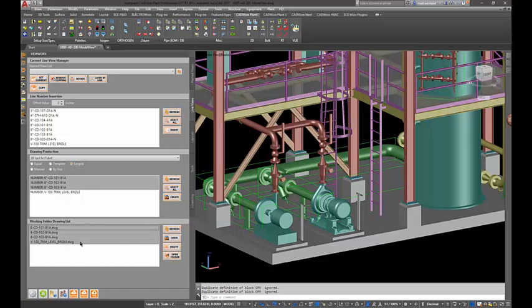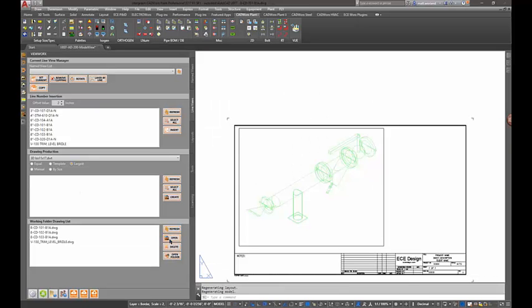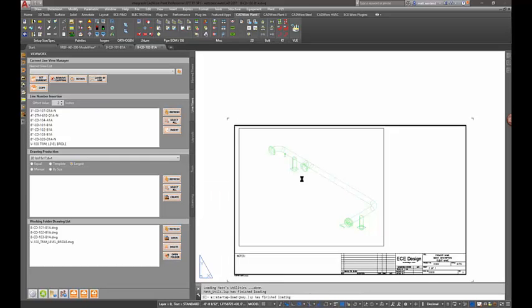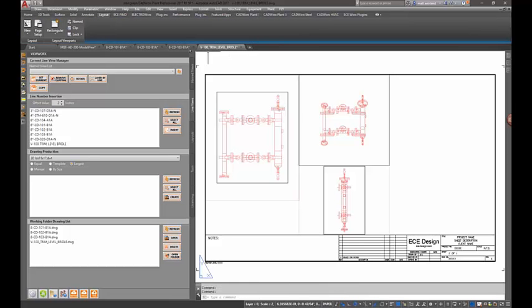Now let's go through and open this up. As CADWorx opens these up individually, you'll see them flicker by on the screen. Here's our first drawing, our second drawing, our third to finish out the piping route going into the vessel, and then finally the trim drawing. These three drawings up here are going to function very similarly, so we'll just annotate and work on one of those. But first let's work on this trim detail in a different style here.